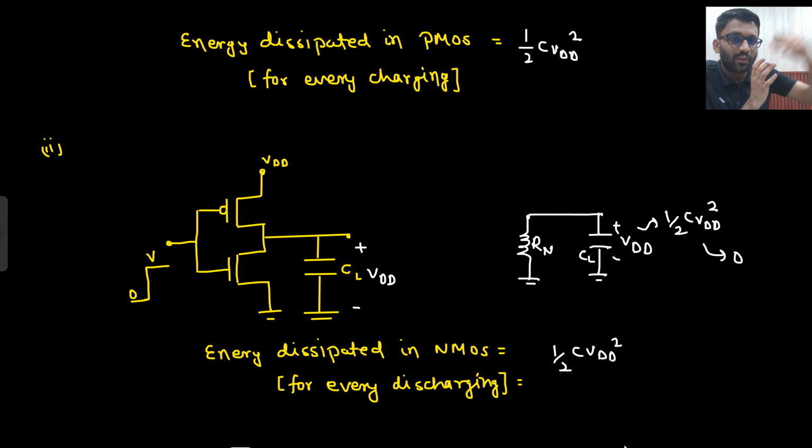So if you see at a top level, you will find that this CL is depending on the design parameters of this one as well, because this CGD and all these capacitors that we call parasitic cap would depend on the design parameters of this particular CMOS, right? So someone will have this doubt that, sir, the CL is depending on these caps as well.